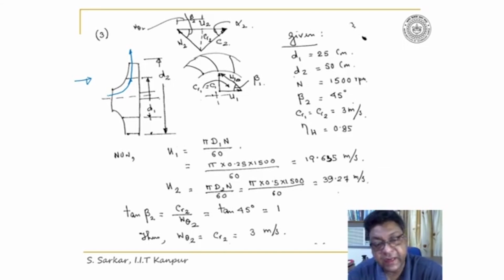So I have taken another view where I have illustrated the flow passage. If I consider this is the direction of the rotation, the vane will be curved in this direction. That is why it is named as backwardly curved, as illustrated in the lectures. So this is the blade passage, and I have drawn both the inlet velocity and the exit velocity.